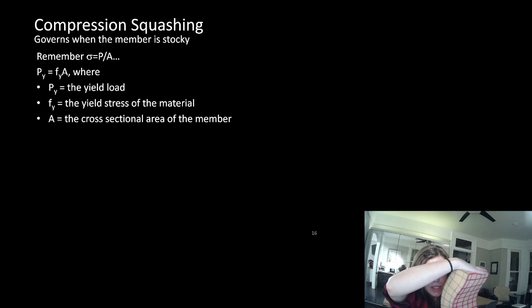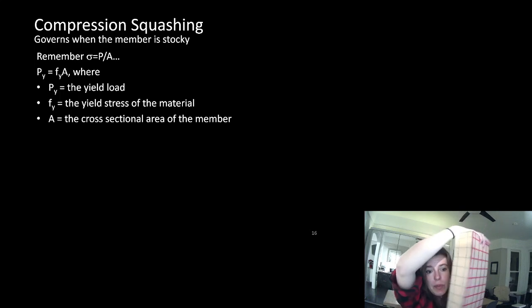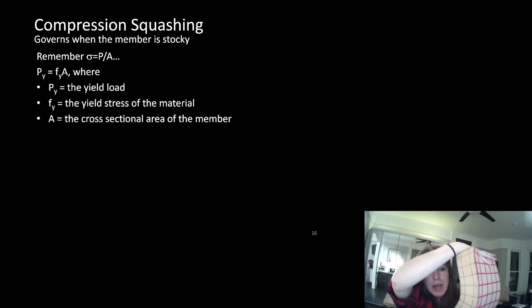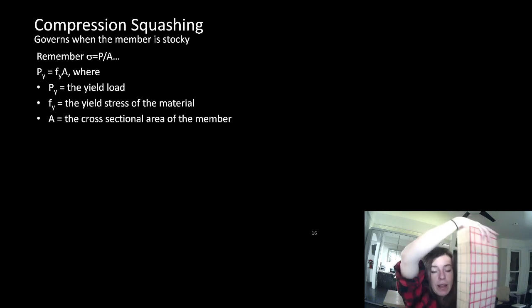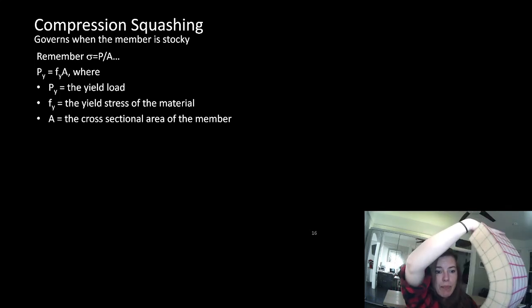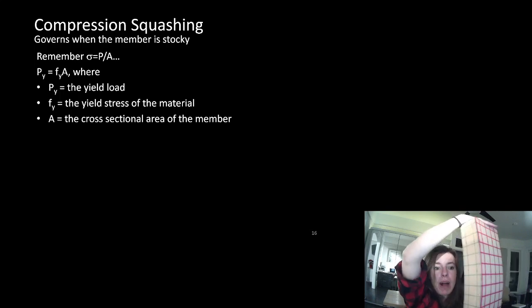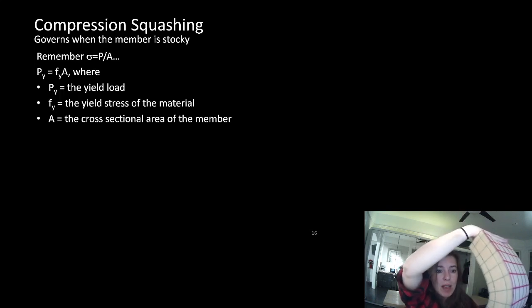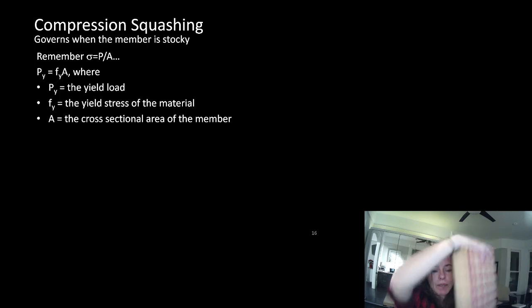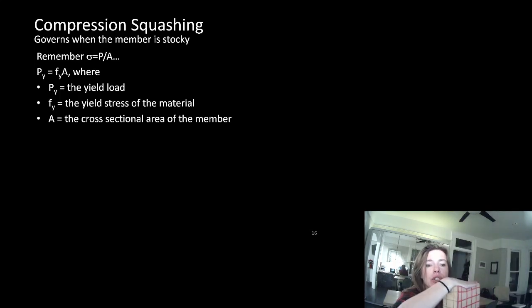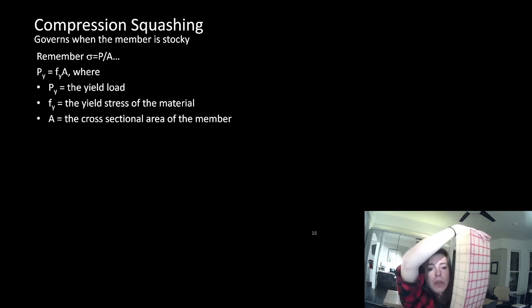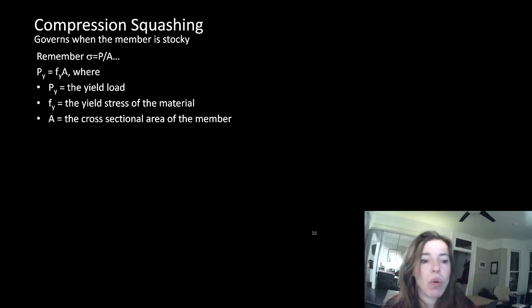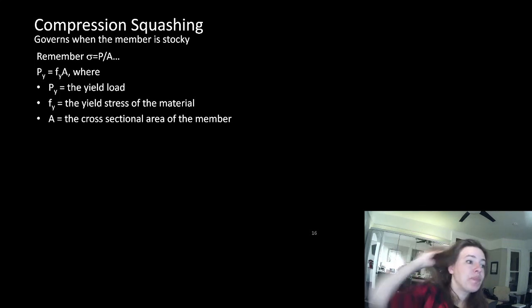I'm not doing that. It's doing it on its own. So I make it a little bit longer. It squashes a little bit, and then it buckles right away. And then when it's really long, I barely get any squashing. You can see that I don't even really get the opportunity to squash it. It buckles. So it looks like when it's short, it squashes beautifully. When it's at the halfway height, it squashes some, and then it buckles. And when it's really long, it doesn't squash at all. It just buckles.